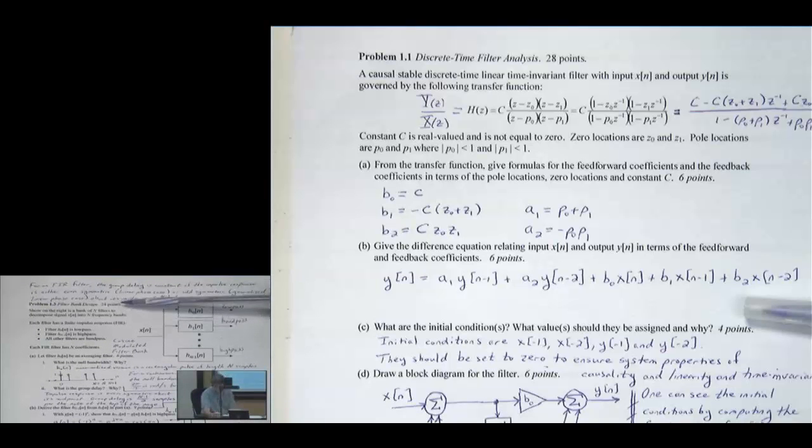So it's a filter bank design. Shown on the right is a bank of n filters to decompose a signal x of n into n frequency bands. Now, I don't tell you here they're equally spaced, but they will be equally spaced. Each filter has a finite impulse response. H naught of n is my low-pass filter. The last, H sub n minus 1 of little n, is the high-pass filter, and then all the other filters are bandpass.